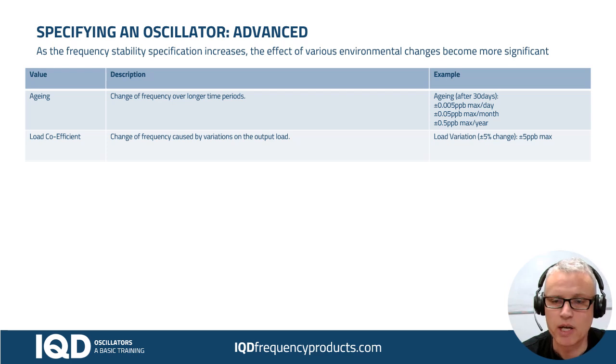as a maximum change in frequency that you could expect. So that gives you an indication of what's happening on your PCB and why you might see a frequency different to the frequency that we told you it was going to be. Might be because there's a different load in your PCB to what we had in our test circuit as we designed it.